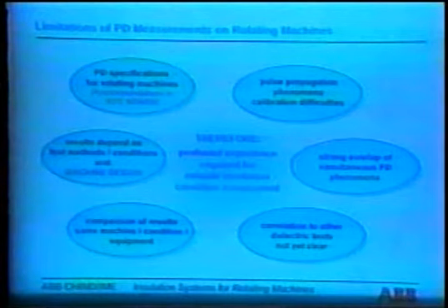We have strong overlap of simultaneous PD phenomena within the winding. The correlation to other dielectric tests is not yet clear. The comparison of results is only valid under special conditions. It is valid for the same machine under similar conditions using the same equipment, and the results will very much depend on the test method we use and on the conditions during the measurement. And especially, what is most important, it will depend very much on the machine design.